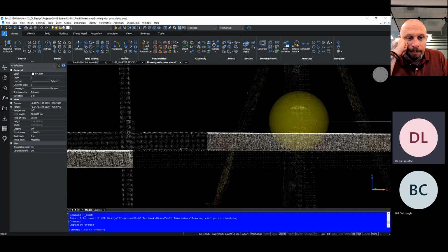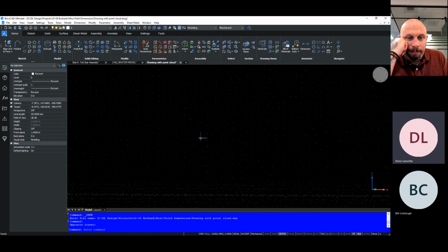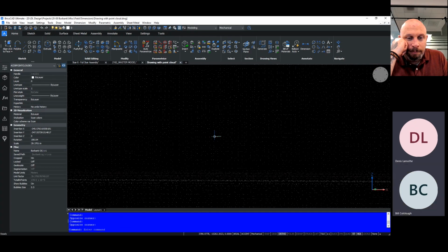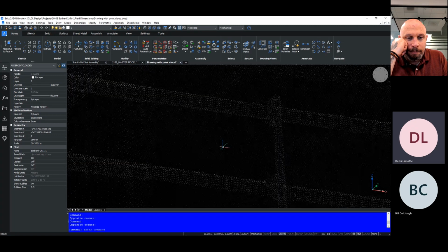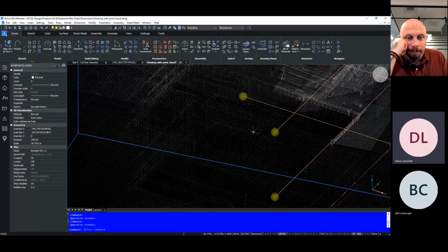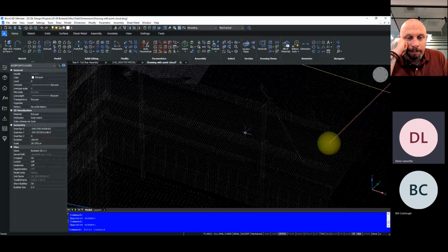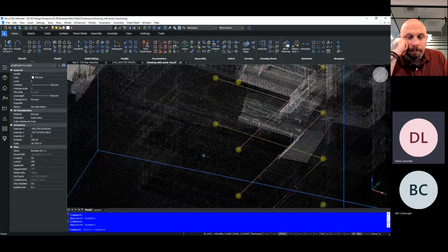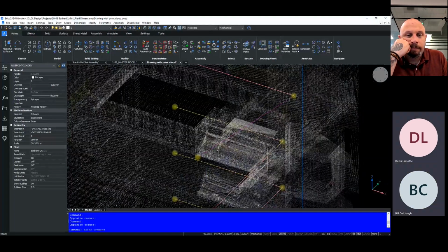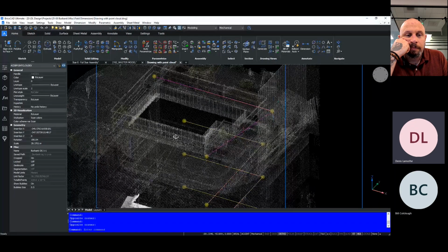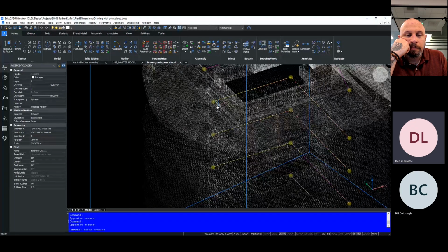It'll take a series of measurements, like little dots, as this laser is spinning around and moving left to right ever so slowly. All these tiny dots are registered in 3D in the system, and each is assigned a color based on the camera so that it knows what the object looked like when it was captured. Then when you look at the point cloud, you can make out better what was scanned.